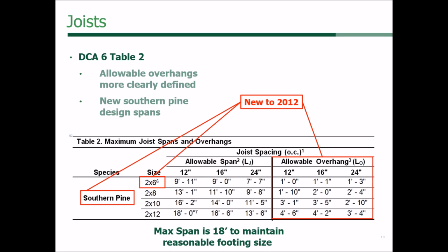We also max out the spans at 18 feet just to make sure that our footing sizes are reasonable and you don't end up with such a huge footing that no one wants to dig it.